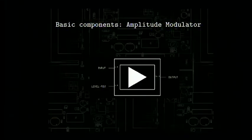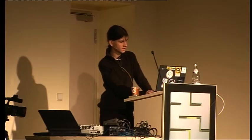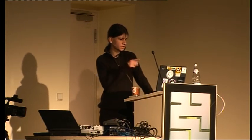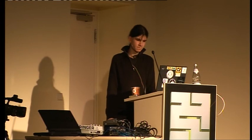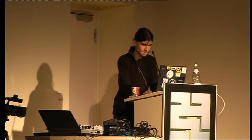Here is an amplitude modulator. This is kind of an amplifier. So you can control it, for example, with a LFO, a low frequency oscillator, and can make the tone fall off if controlled by an envelope generator, or make some rhythmic effects.